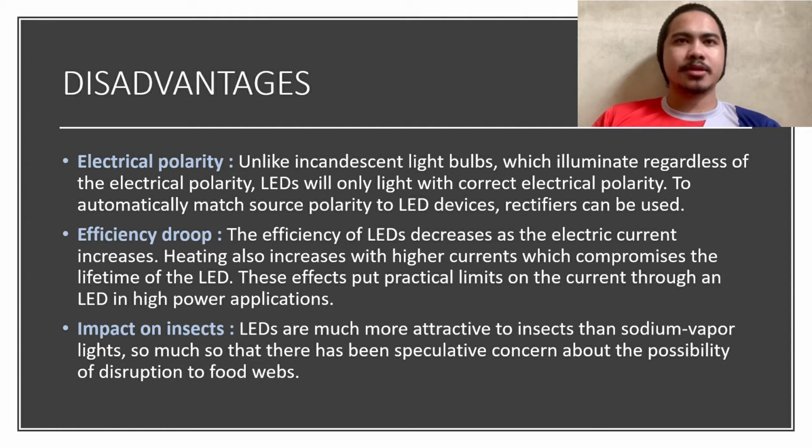Okay, efficiency drops. The efficiency of LEDs decreases as the electrical current increases. Heating also increases with higher currents, which compromises the lifetime of the LED. These effects put practical limits on the current through an LED in highest power applications.